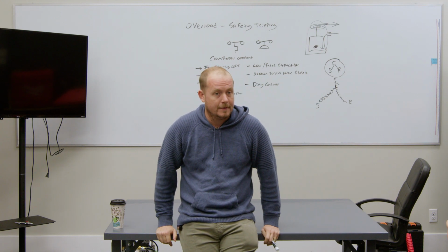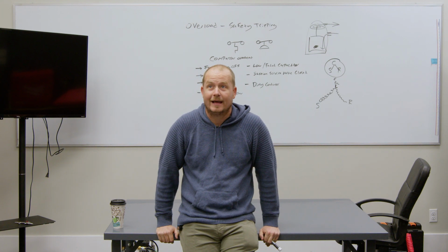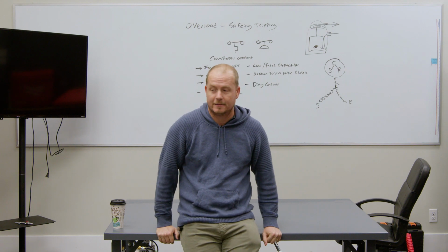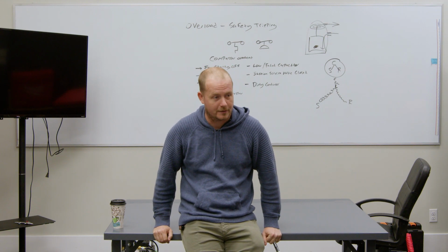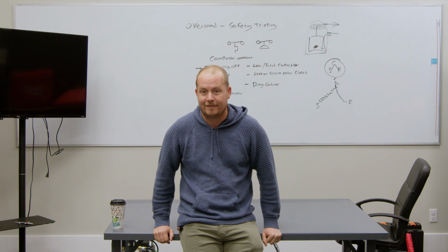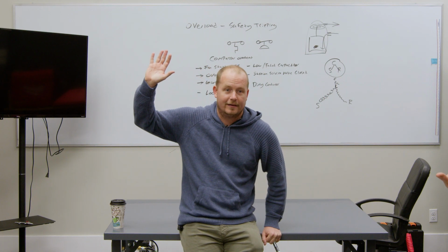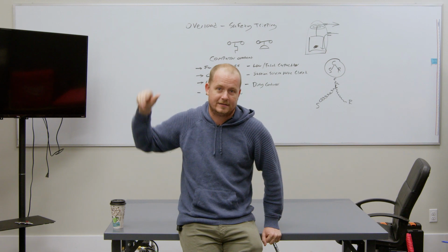It could be something as simple as you bumped the float switch and the fan was running backwards. Yeah, and that can happen. It could be something as simple as you bumped the float switch and it was a scroll compressor, and the scroll compressor started running backwards until it went out on thermal. And I've had so many people tell me that that's impossible and that doesn't happen. Anybody here seen that happen before? Just all the hands are raised. It happens.